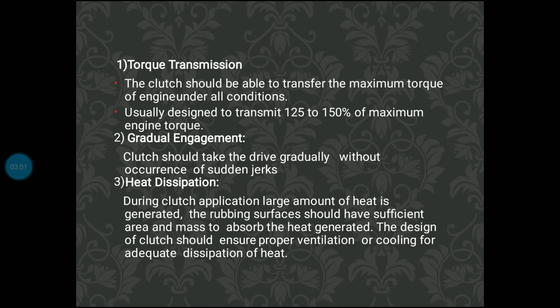Heat dissipation. During clutch application, a large amount of heat is generated. The rubbing surface should have sufficient area and mass to absorb the heat generated. The design of the clutch should ensure proper ventilation or cooling for adequate dissipation of heat. When the clutch is engaged, the maximum heat will be generated. So for that purpose, the surface of the driven shaft or driver shaft must be sufficient to absorb the heat.